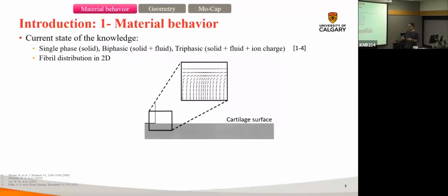Fiber remodeling is when you assume that fibers are randomly oriented initially, and then you apply forces based on a criterion like maximum principal stress or maximum principal strain. You change the direction of these fibers by a small degree in each increment, and then see if this fiber orientation converges or not.